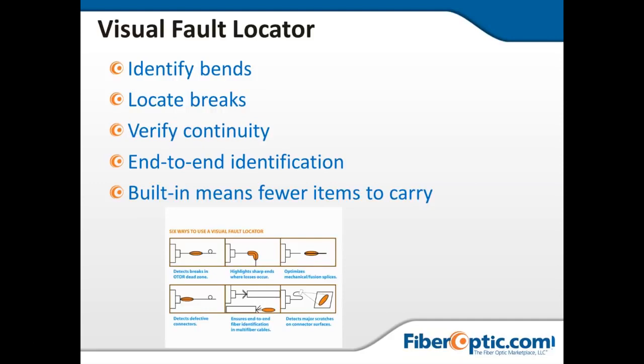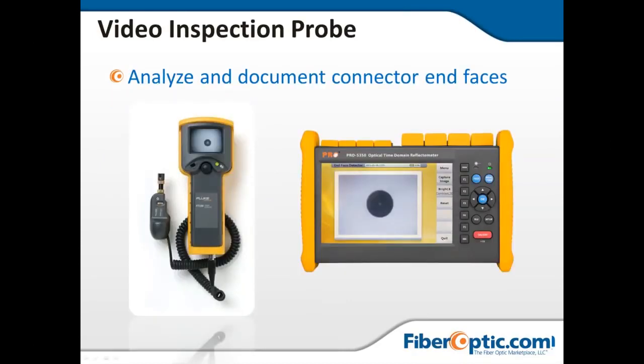Some of the other things that I also identify, it detects scratches, I think, on a connector. So one of the things that I've been able to do is put it on the back of a connector, and don't point it at your eye, but you point it up in the air, straight up into the air. And if you look at it at a 90-degree angle, like from the side, if there's a little star at the top of your ferrule, there's dirt or debris there. If you wipe that clean, you shouldn't see any kind of star or reflection right at that point. If I didn't have a microscope, I've actually been able to clean connectors or tell whether they were dirty by looking at it and detecting scratches or debris on the end of the connector. So just very, very good ways of using a visual fault locator. So if you can get it built onto the OTDR, why not?